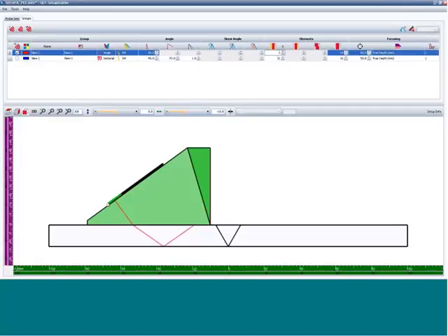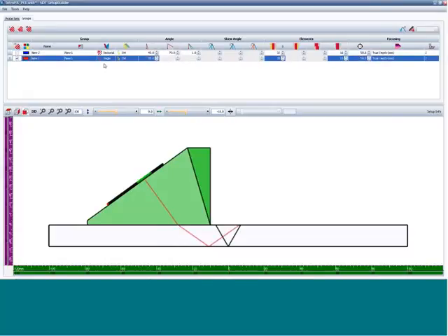Here is probe element 1, probe element 16, and we have a 55-degree refracted angle being generated into the material. Obviously, if I start the element at a higher position, it's in a better position for the inspection. This is a static single focal law, and here we will see the full sector scan.